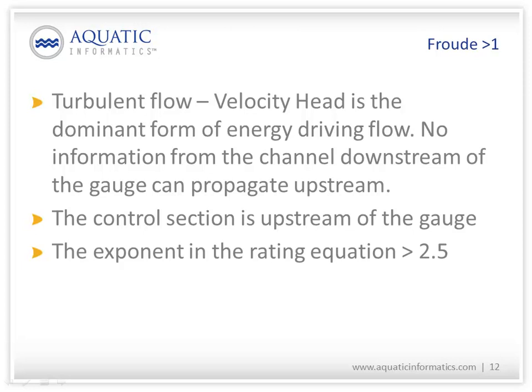And so these are not great gauging locations for a number of reasons. One is it can be very difficult to maintain gauging equipment in a turbulent flow regime. It can be very difficult to monitor stage. There's a lot of noise in the stage signal. There can be a lot of aeration of the water, so our assumptions about water density become invalid. But more fundamentally, we've got a violation of our assumption of uniform flow. In turbulent water, the flow cannot be uniform. So these are not great gauging locations, and we would choose to avoid them, but it's not always possible.